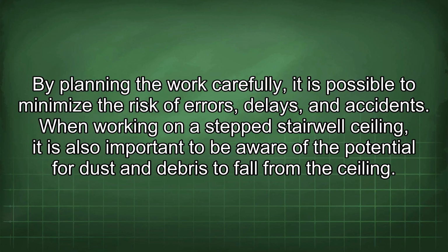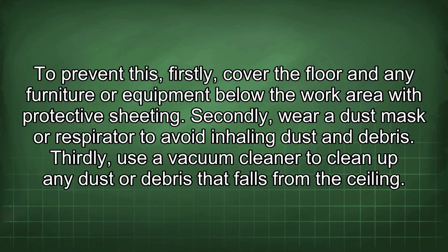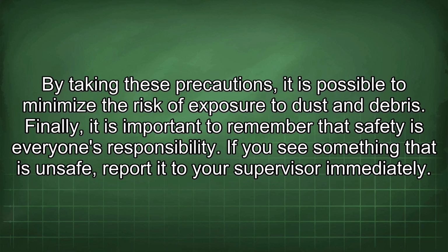When working on a stepped stairwell ceiling, it is also important to be aware of the potential for dust and debris to fall from the ceiling. To prevent this, firstly, cover the floor and any furniture or equipment below the work area with protective sheeting. Secondly, wear a dust mask or respirator to avoid inhaling dust and debris. Thirdly, use a vacuum cleaner to clean up any dust or debris that falls from the ceiling. By taking these precautions, it is possible to minimize the risk of exposure to dust and debris.